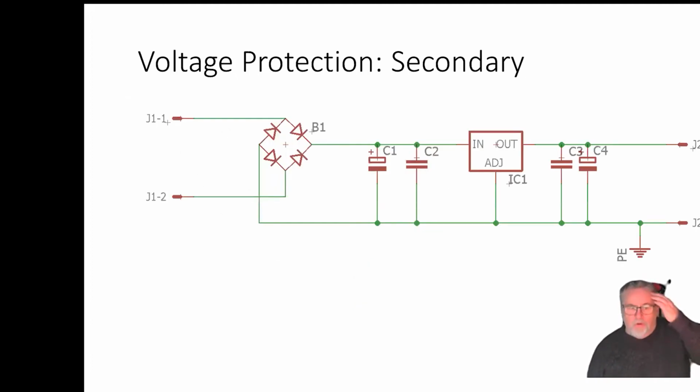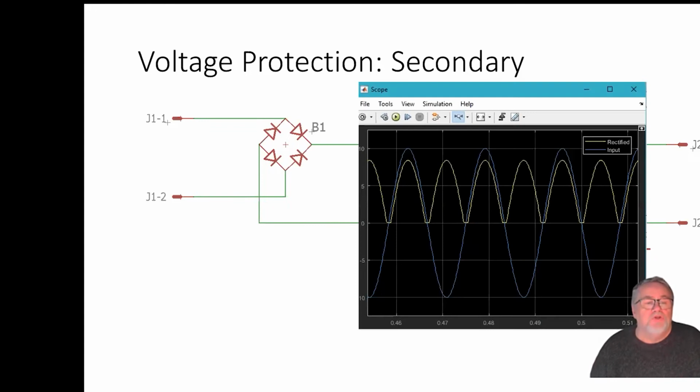There's the circuit that we all know and love. And I'm going to move through it from left to right. We assume that we've got AC going into the bridge rectifier, typically from a transformer. So the output of the bridge will look like that. The input's in blue, the output's the rectified output, so-called full wave bridge rectifier. And you get these lumps. To get the energy between when the lump isn't there, we put a capacitor in.